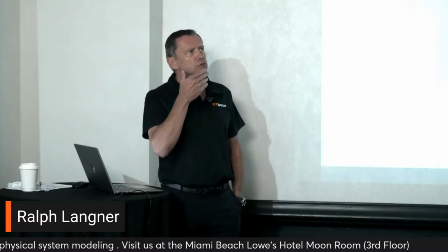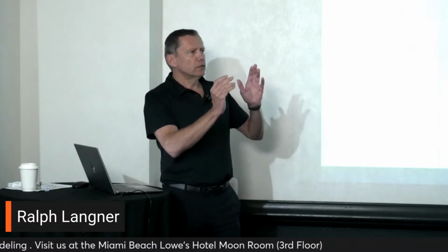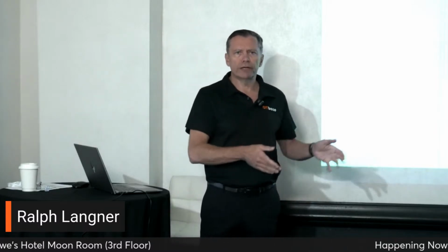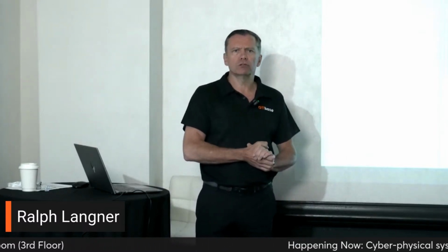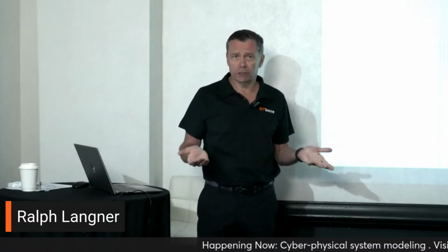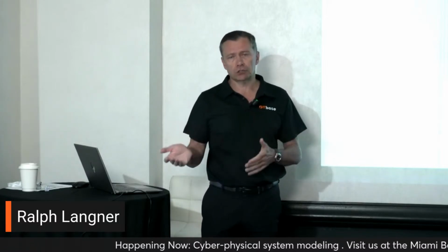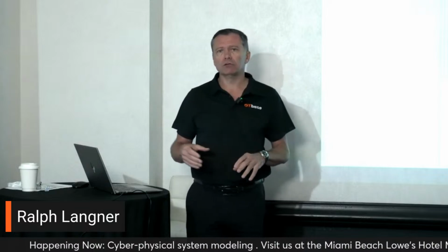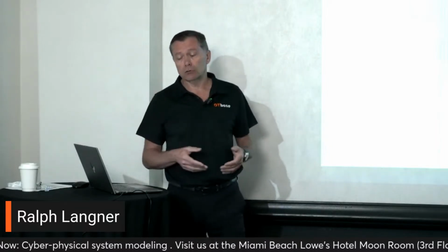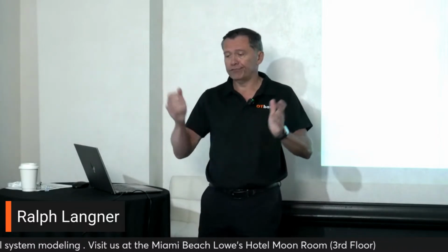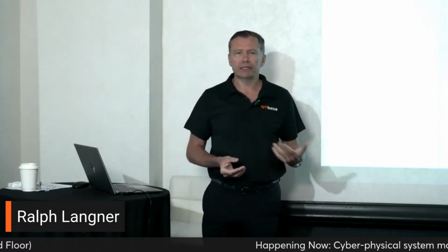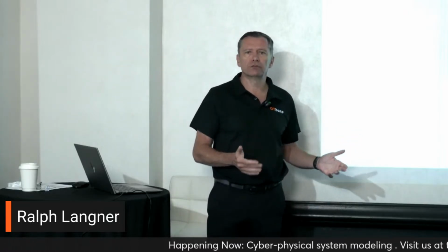If you would say, well, this Rockwell control module here, or this Rockwell rack, this must be pretty critical because it's a PLC. That's nonsense, right? It all depends on the function. And in real life, it goes even beyond that. You couldn't even say, well, there are, let's just say, 50 or 10 I/O modules in there, so it must be important. No, that's not a thing. You have to analyze the functions that are executed or controlled by this particular rack.